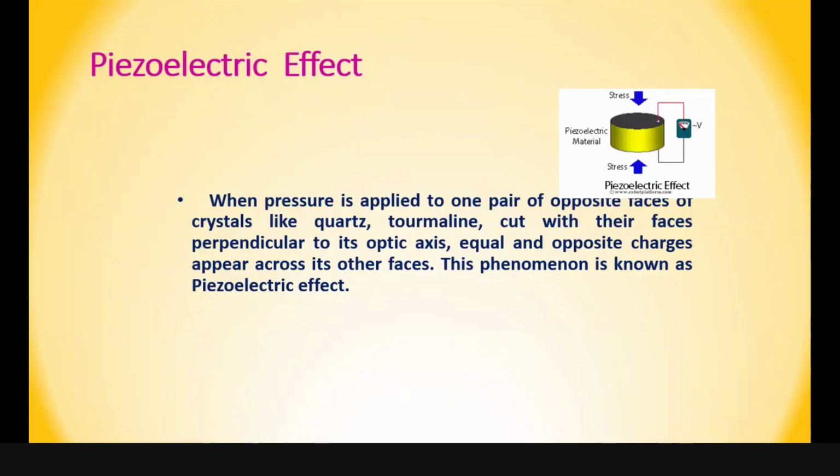Piezoelectric effect. In the lab, some of you must have studied this piezoelectric effect. See, a few crystals, a few materials like quartz and tourmaline are piezoelectric materials. If I have a lump of quartz or a lump of tourmaline, it will not act as a piezoelectric material. I have to cut it in such a manner that it behaves as a piezoelectric material.